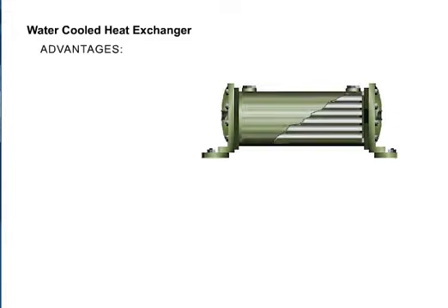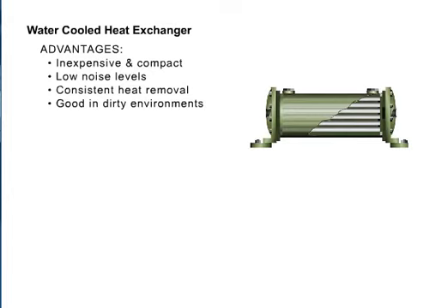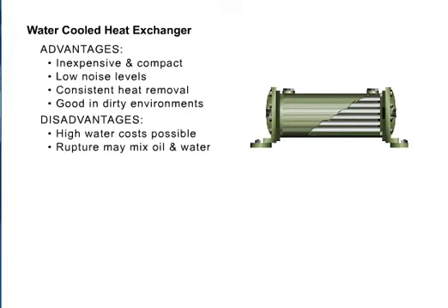There are advantages to this type of cooler. They are the least expensive, they are very compact, they do not make noise, they provide consistent heat removal year-round, and they are good in dirty environments. The disadvantages are, water costs can be expensive. With rupture, oil and water may mix, and usually require regular maintenance from mineral buildup.